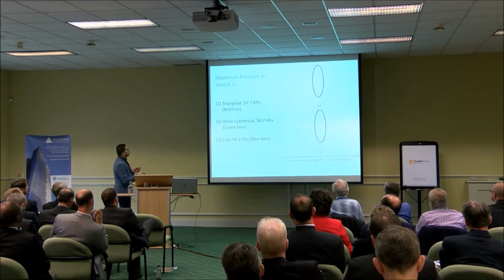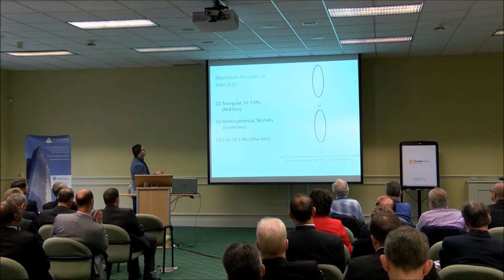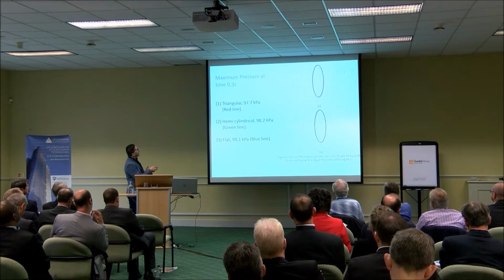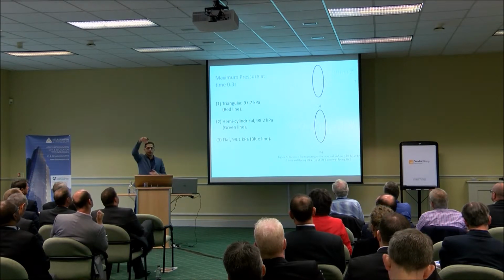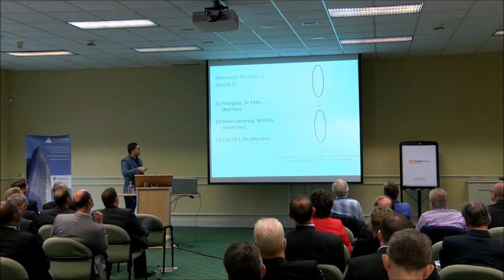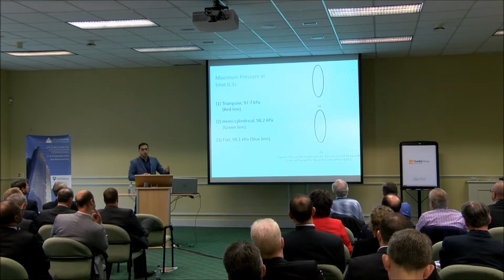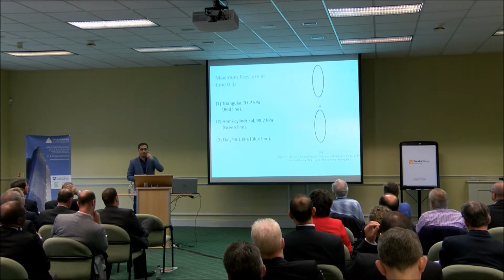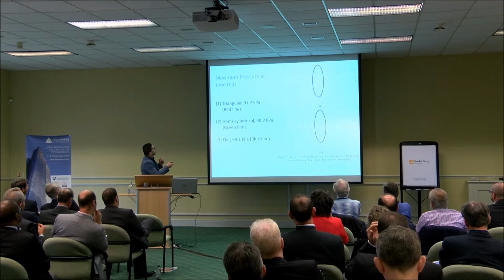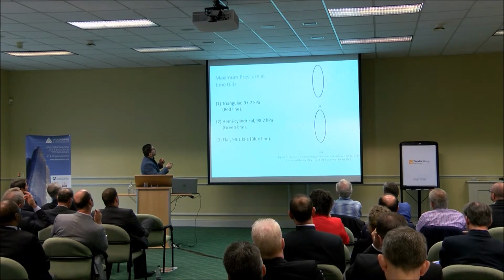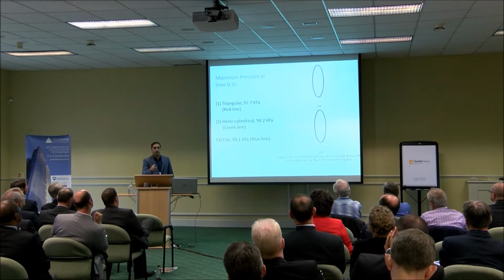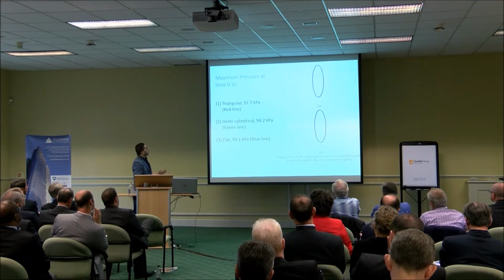These two graphs show the pressure fluctuation over the side walls of each lift. Graph A is for lift number 1, which is going downwards. Graph B is for lift number 2, which is going upwards. For those who sit in the back, the vertical axis is the pressure. The horizontal axis is the real time, from 0 to 0.6, which is not the simulation time.